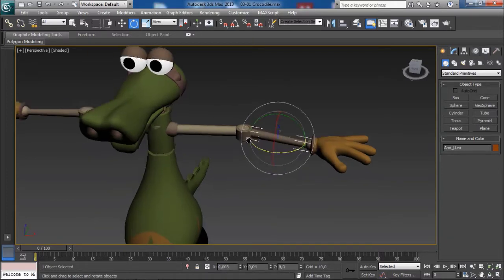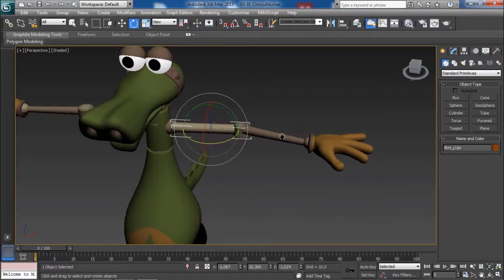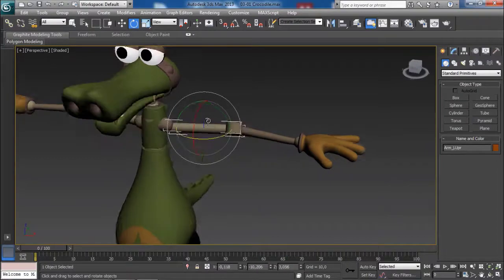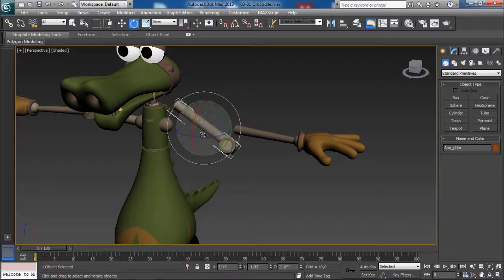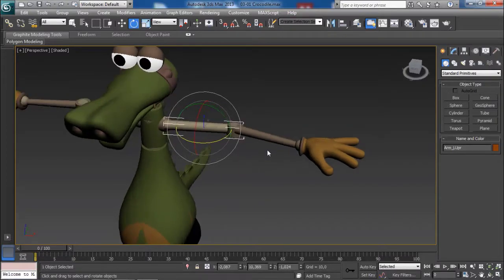And that's why we are getting this result. The same thing would apply to the upper arm that is moving along and which should drive the forearm and the hand along with it. But as you can see, it is moving along without affecting the others. So to fix this, we need to set a relationship between our objects, and we do so through linking, or another term you may be familiar with is parenting.